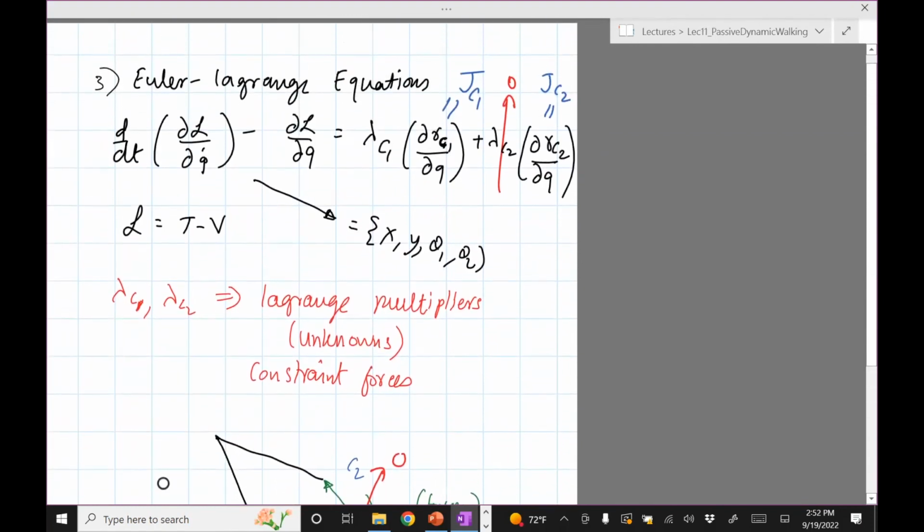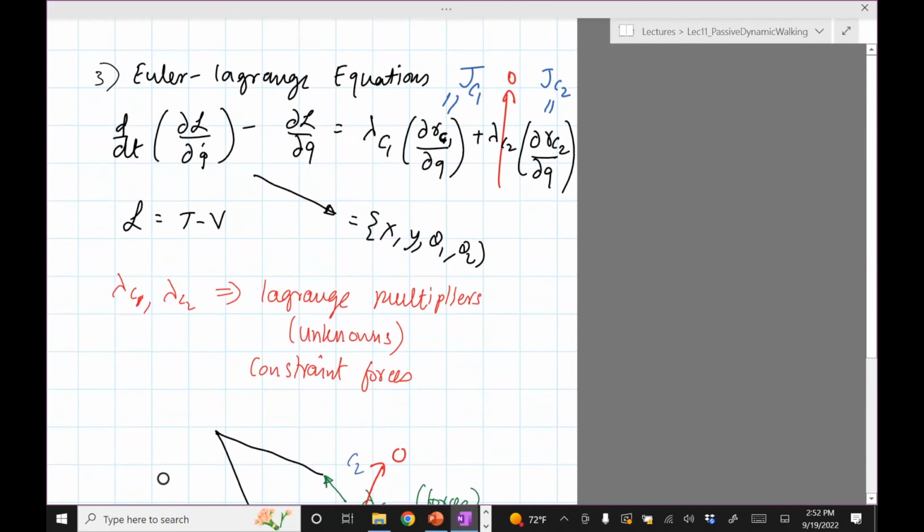So what we do is we take these equations. Now, you can see that Q has 4 degrees of freedom. Those two, x and y, which are not there in the double pendulum, appeared here because we used a floating base. It turns out that when you take the derivative, you have not 2 but 4 equations, just because of the floating base.